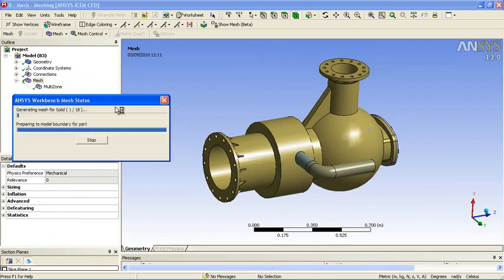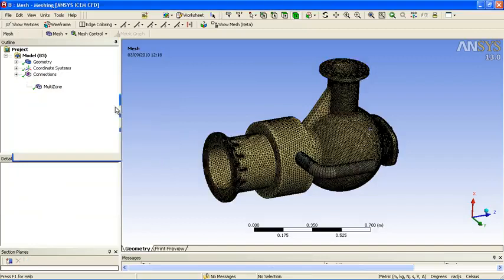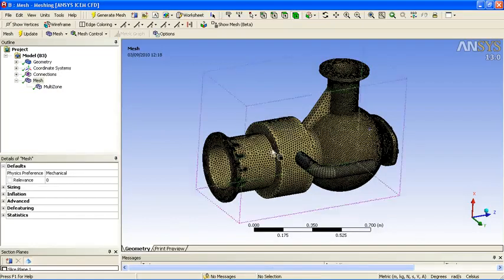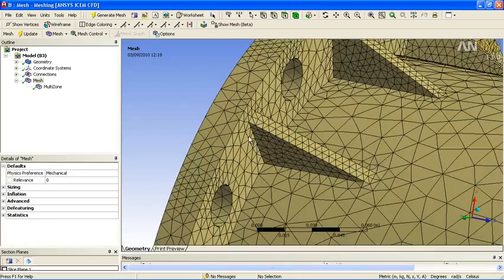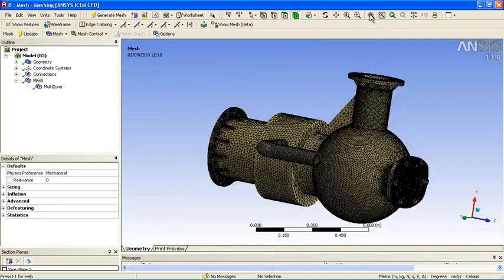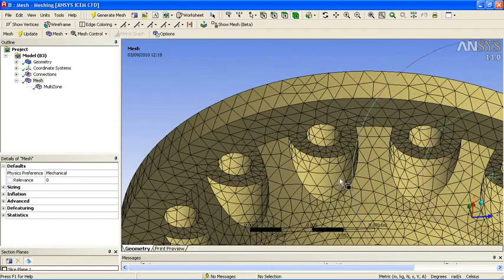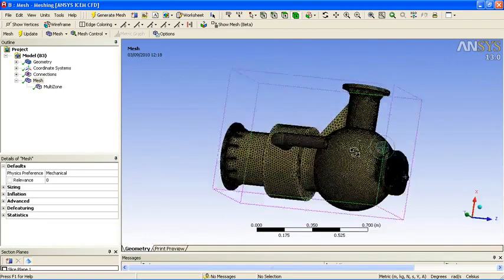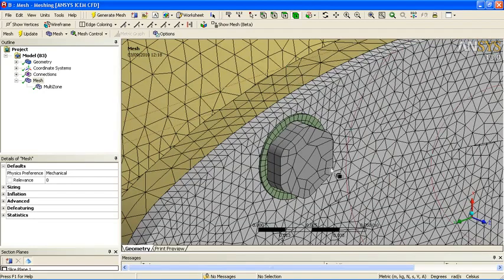We will keep all of the other settings the same, so proximity-based meshing, with exactly the same parameters that we used before. And then we will generate a new mesh. With the persistence of the meshing inside ANSYS, it's very easy to remove a feature, regenerate the mesh, and see what effect this has. So here is our resulting mesh. You can see much more efficient use of cells in these regions. Again, we really have radically reduced the node count in these areas with a heavy amount of fillets. And also you can see a hexahedral mesh generated for the bolt.